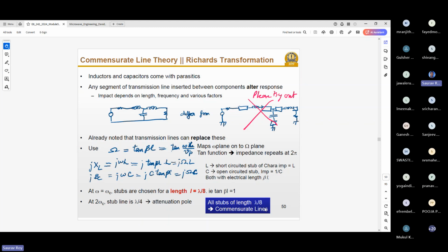Some of you who have worked with hardware or PCB hardware will know that on top of a substrate, you cannot solder these components unless you have a metallic pad or metal. If you have a microstrip line already present, you can solder on top of that. But where you have only substrate, no metal, you cannot solder a component there. You might say, okay, I will put some metal there, the soldering elements, and then put it.